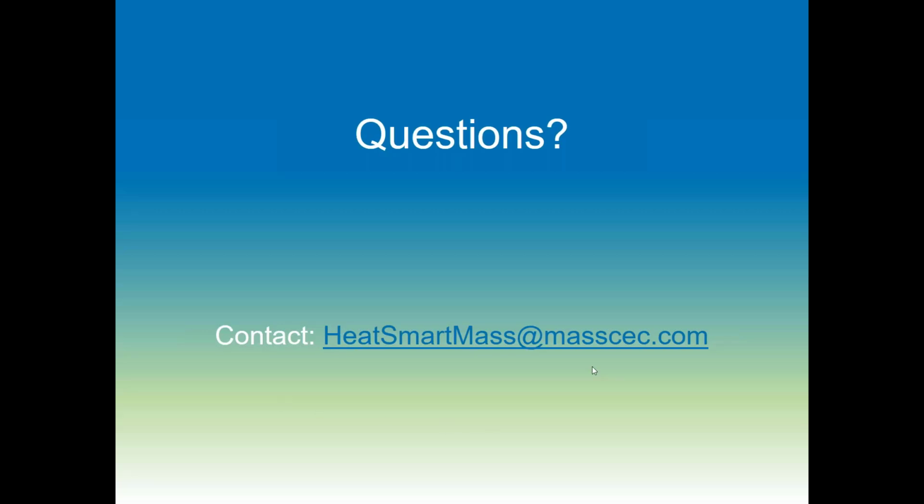We have a question about maintenance costs for each technology or maintenance requirements. As a generalization, as long as these systems are well maintained, there's minimal maintenance required. So certainly heat pumps have a reputation for having low maintenance costs as long as they're properly installed and maintained by the system owner. For example, for an air source heat pump, that might mean changing out the filter periodically. But besides that, the requirements are pretty minimal. Certainly for solar hot water systems, there's minimal requirement. Also, you might have to shovel them off in the winter.